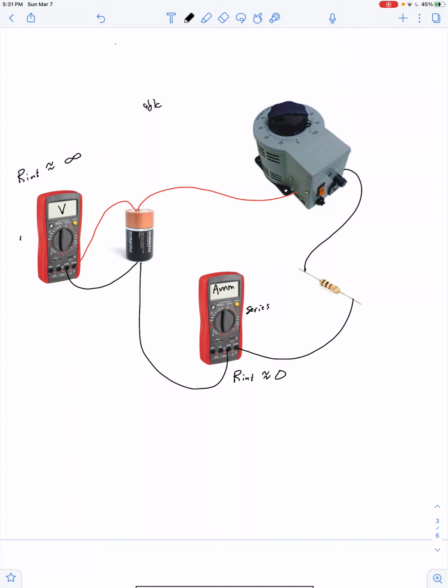Likewise, if the voltmeter was like an ammeter and had zero resistance, then this junction right here says current could flow to the intended part of the circuit, or the voltmeter itself represents a loop through which current could flow. Well, if the resistance of the voltmeter was practically zero, then all the current would take that path, and of course smoke would start to billow out of this voltmeter.